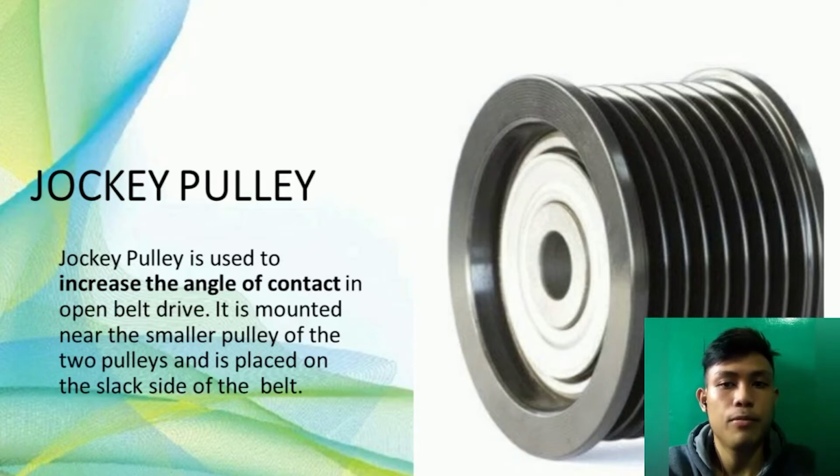The next type is the jockey pulley. It is an idler pulley and is used to increase the angle of contact in an open belt drive. It is mounted near the smaller of the two pulleys and is placed on the slack side of the belt. The increase of the angle of contact will lead to increased power transmission capacity of the drive.